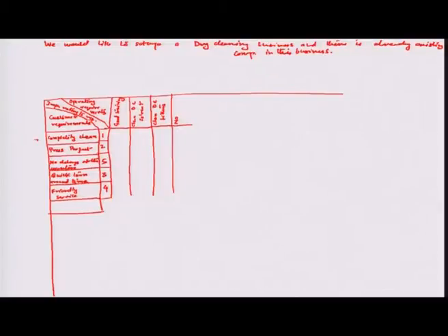One must ensure that there is no rust on these lines, because they are typically hidden behind the machine, and so there has to be some kind of preventive maintenance or a strategy to look into it. So let's write this as one of the operating requirements: no rust in fluid lines. Let's call it solvent lines. So that's another operating requirement.